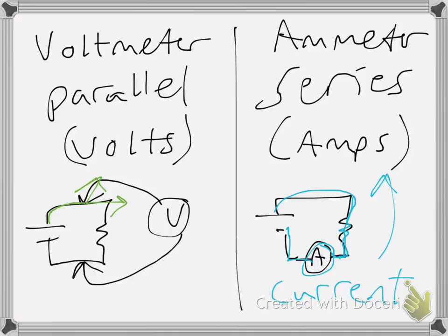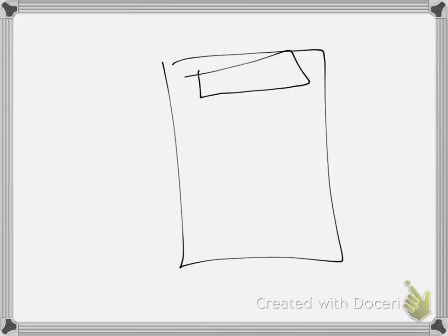When you want to use a voltmeter, you're going to measure volts. To find voltage, you just stick your voltmeter somewhere in the circuit on whatever you're trying to find the voltage of. Now that brings us to our physical voltmeter. We have a multimeter, which means it's capable of measuring both DC and AC voltage, current, and ohms. So we have a V with a little squiggly, then a V with a solid line, then an A, and then an omega.